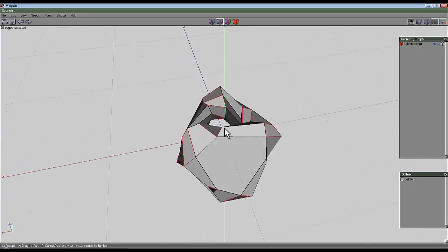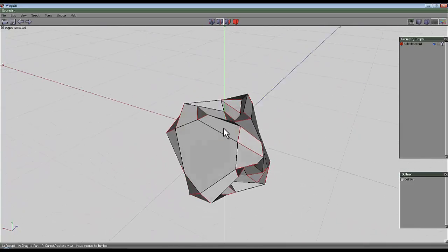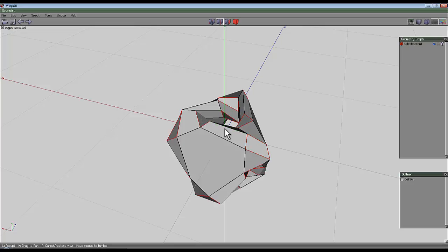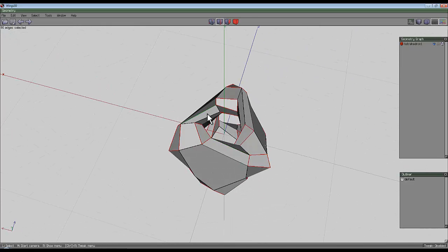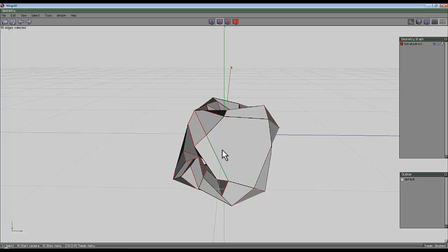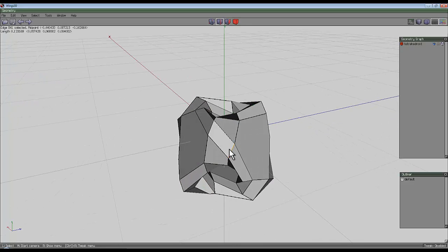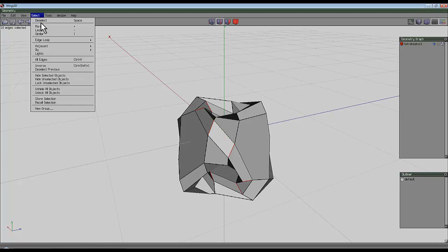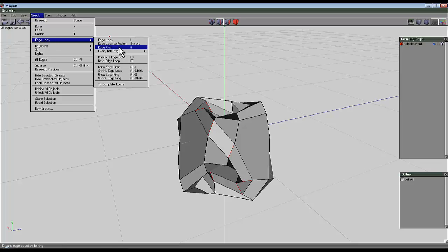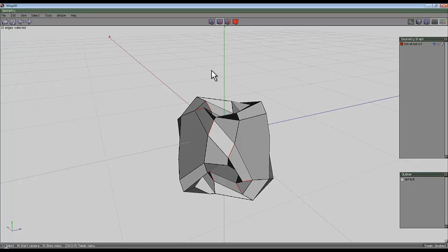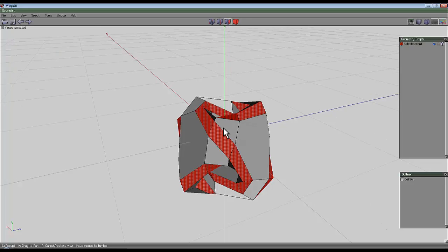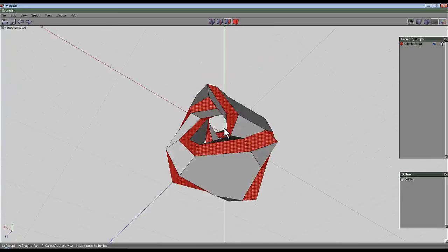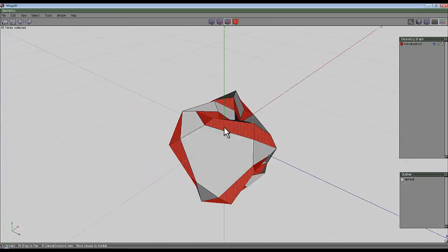So at this point I am looking for these paths that go around from one object part to the other. So there's these faces and there's these paths that separate them. If I select an edge on there and press G to propagate it round those edges. Oh, I can never remember the name of this command. It's an edge ring, right, and I for identical, so I get the ones that are corresponding on the other faces, and then select face. You can see how those faces loop around and sort of connect again.